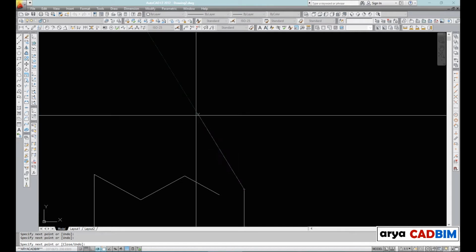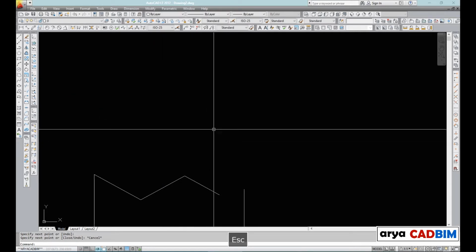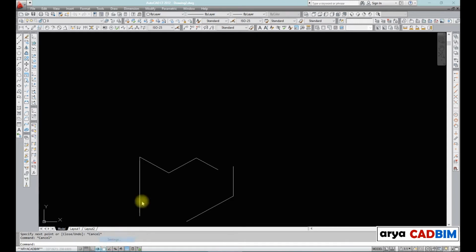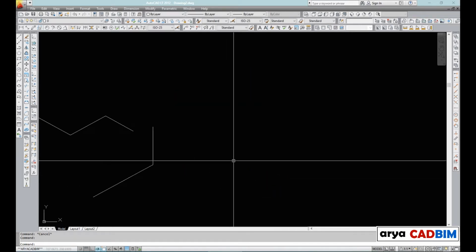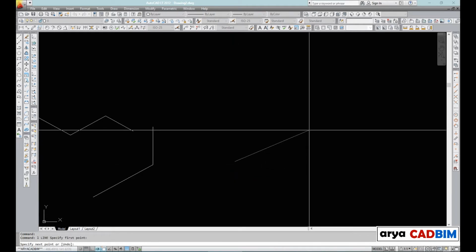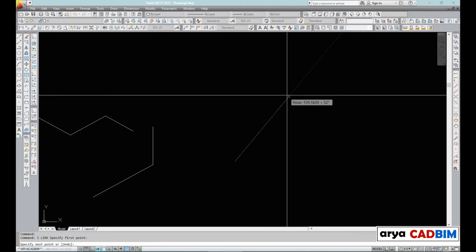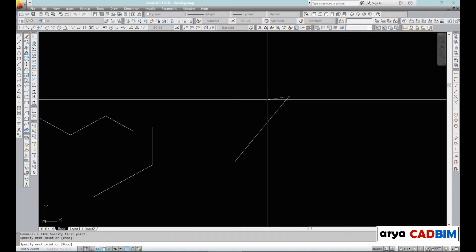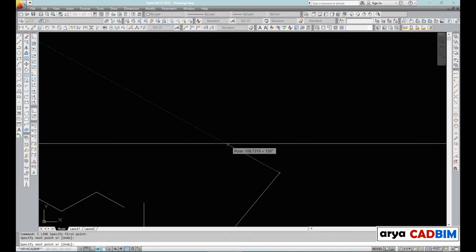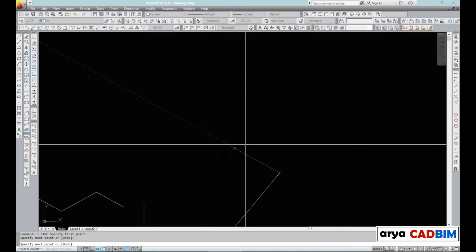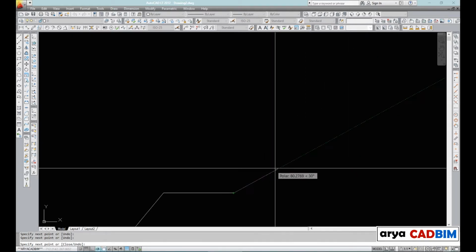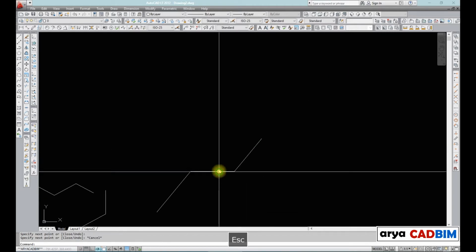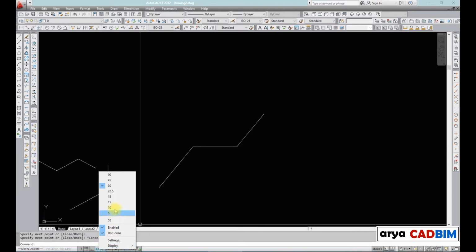If you define an additional value, then that value, only itself, will also be added to the options. For example, let's say we want a line at the angle of 52. Go to Additional Angles and assign New as 52. OK and exit. Now you will see 52-degree alignment besides 30-degree intervals. You can assign the increment degree here with right-clicking to Polar, more practically.